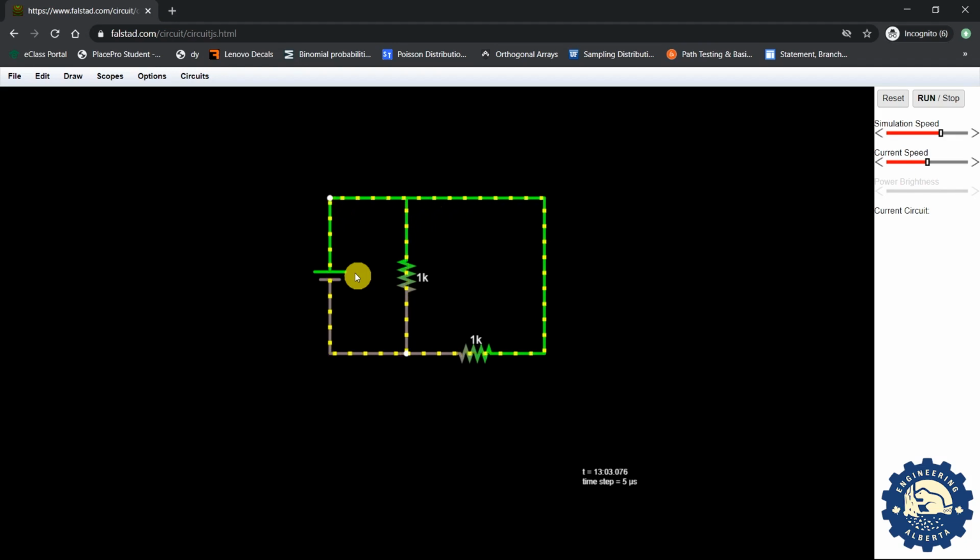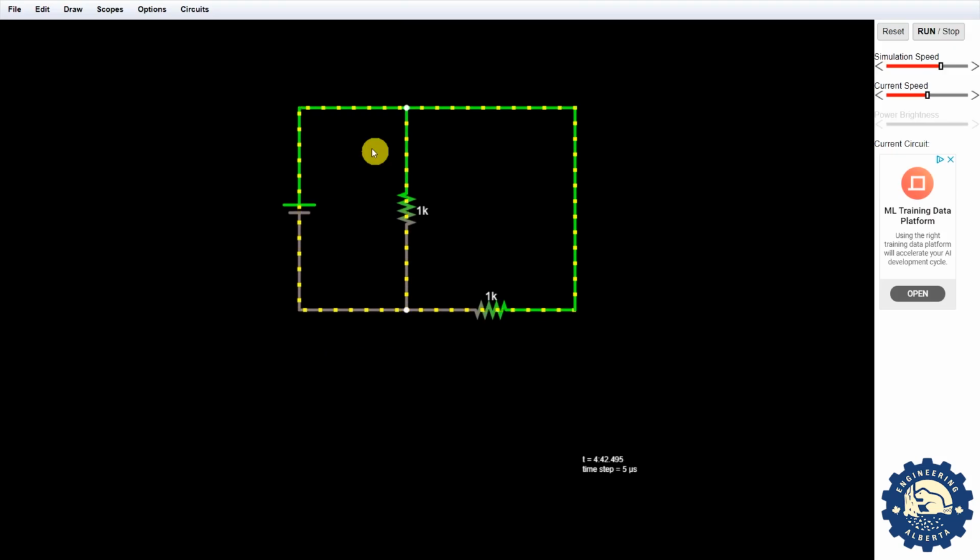If you do not draw the input source with the positive terminal at the top, you will have a whole lot of problems with your wires saying 0 volts and having to swap terminals, which can get confusing. So always make sure the positive terminal is at the top. Right-click on one of the wires and select Edit to show the current and voltage across that wire.